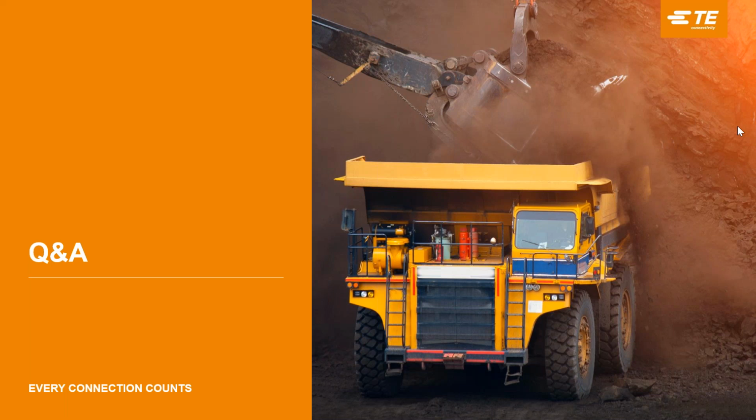And then for DT high speed, because that is a much larger, more robust terminal, easy to hold in your hand, easy to terminate, with a large amount of tooling out there in the field, those are very much able to be field terminated. There is a ferrule crimp and a shield on the cable that must also be crimped, so two hand tools. But that connector is specifically being designed, due to the 40-meter linkage as well, for field repairability. So just to recap, Enet Steel, yes. HDSE net can be done, but you may not want to get involved in it. And DT high speed, absolutely.